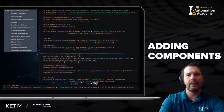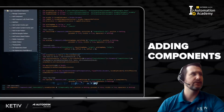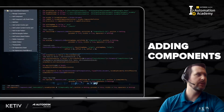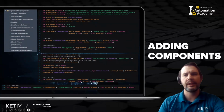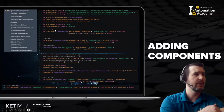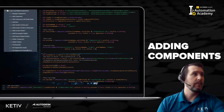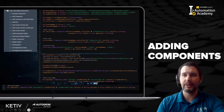Today we're going to look at iLogic snippets that help with adding components. You can see on the screen, on the left, when you have an iLogic rule open, you'll see these iLogic assembly component folders that hold the snippets. You can double click on them and they'll place them into your code where your cursor is. Once you do that, you need to edit it so that it is doing what you want it to do. But today we're going to be adding in components, and we're going to be constraining them.